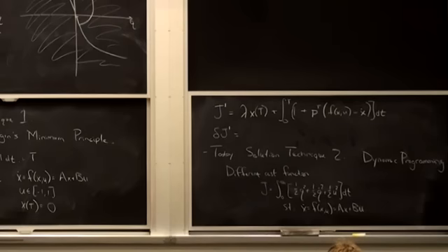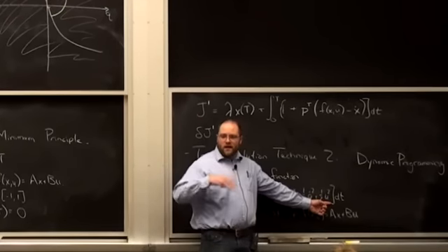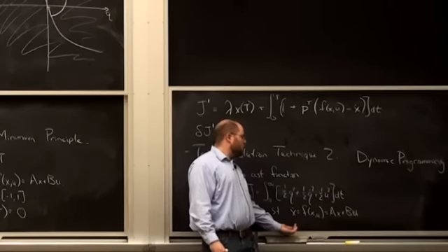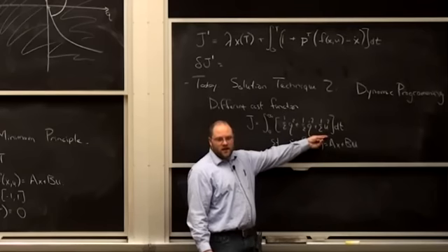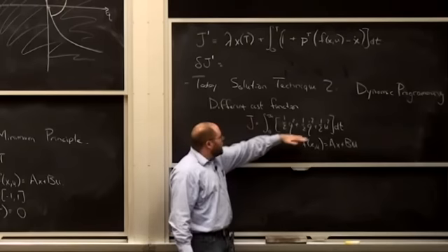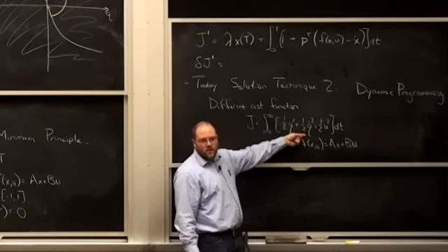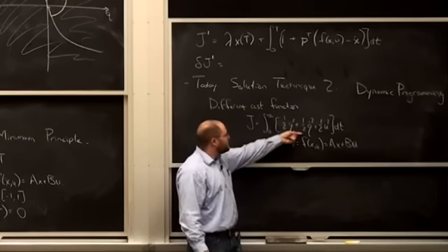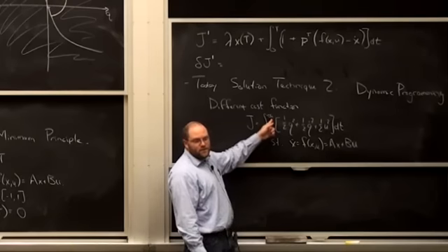It's different in a couple of ways, right? First of all, there's no hard limit on u, but I do penalize for u being away from 0, right? So it's sort of a penalty on u, not a hard limit, okay? And then these terms are penalizing the system from being away from the origin, right? And instead of going for some finite time and minimizing time, I'm going to go for an infinite horizon.